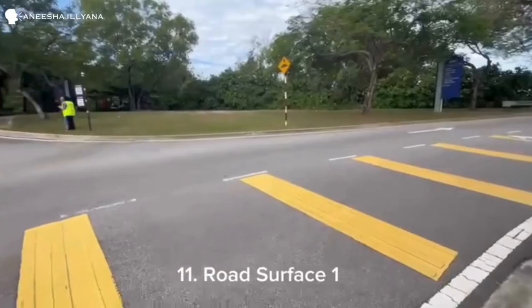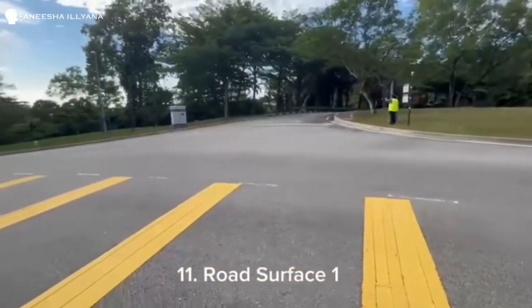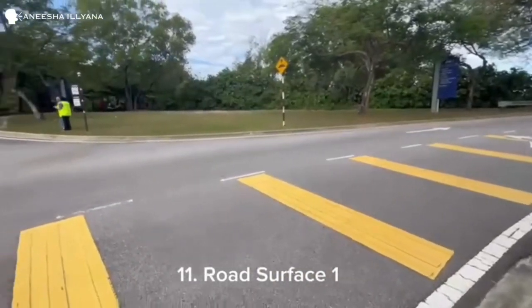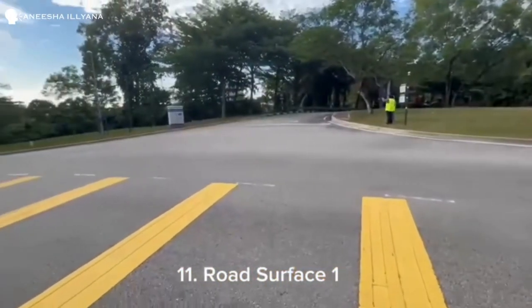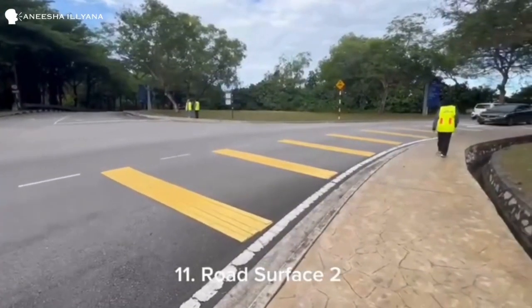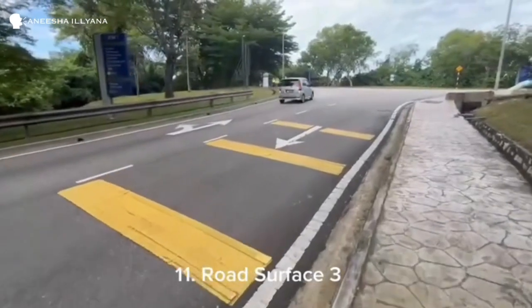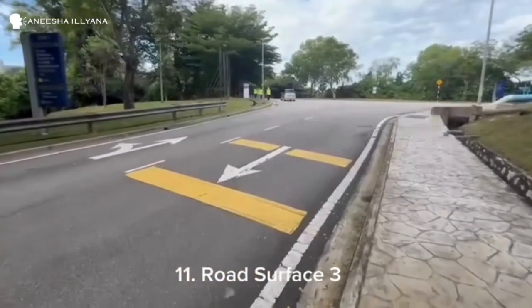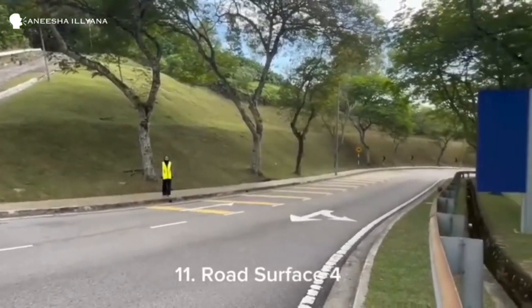Road surface. Based on our observation, the road surface at the selected intersection was in good condition. There were no potholes, cracks, or uneven areas, and water drainage works well without any sign of ponding. The road markings were clear and effective, in compliance with British standards for reflectivity and visibility.